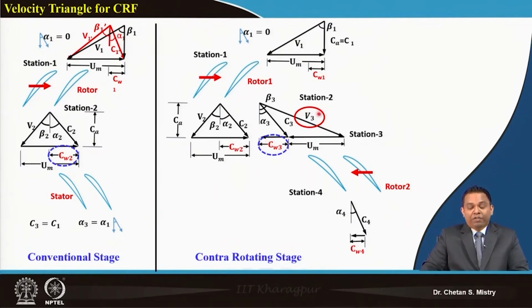How are we utilizing it? If you look here, our relative velocity component at the entry of rotor 2 is going to increase, and that will give you the outlet as per our expectation. So the benefit is the strong suction that happens because of the rotation of rotor 2, which changes the flow field within the gap between the rotors.